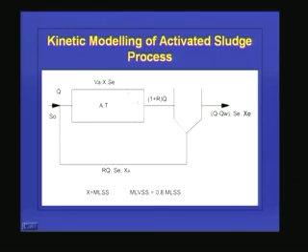That is why we are not giving any X value here. And this is our aeration tank. The volume of the aeration tank is VA, the biomass concentration is X, and the substrate concentration or BOD concentration is SC. We are assuming that this aeration tank is a CSTR, that means a continuous flow stirred tank reactor. So as soon as this S naught enters the system, instantaneously the concentration changes to SC, as we saw yesterday.